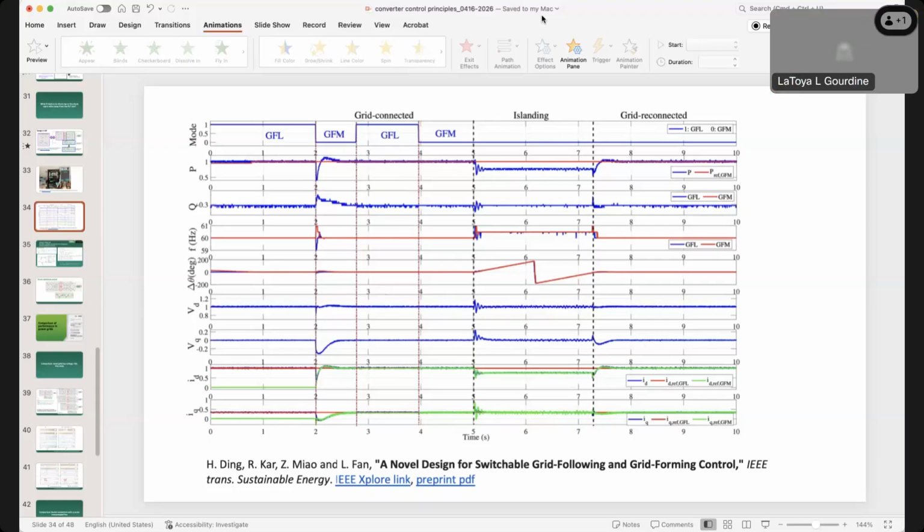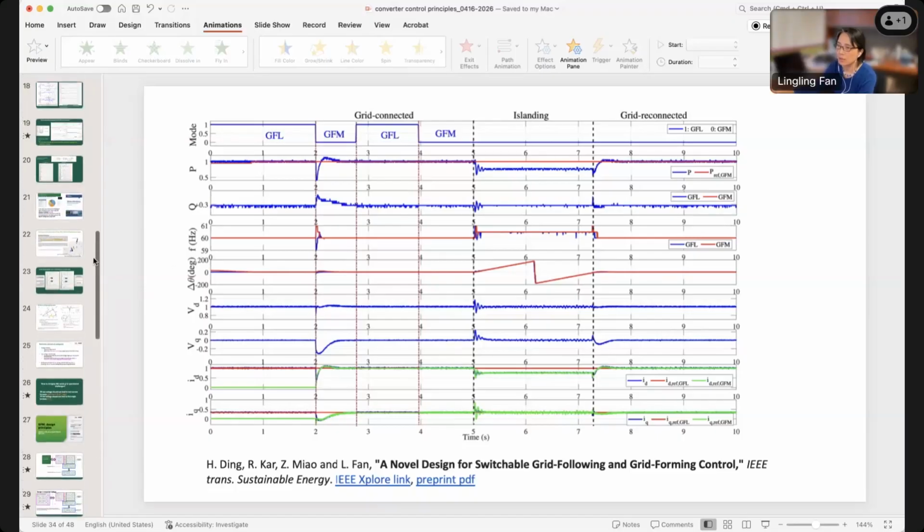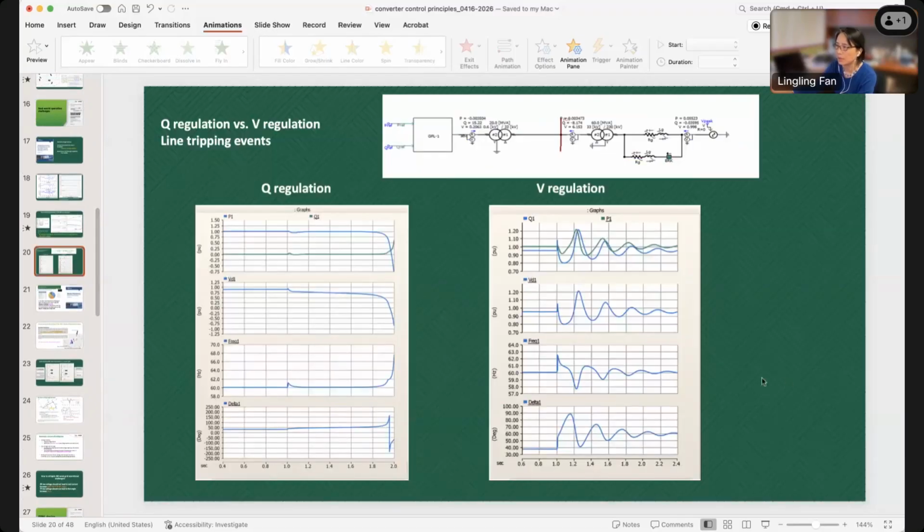What's the main reason for weak grid oscillations? Is it design philosophy that leads to an increase in VD, or is it a smaller PLL bandwidth? Oh, that's the question of why you have weak grid oscillation. There are lots of reasons that we haven't talked about today here. When we see this, it becomes because the system itself is very stressed, right? So you expect to see this if you have designed the voltage controller, the system has a limit. On the other hand, a lot of times you don't see a very weak grid.